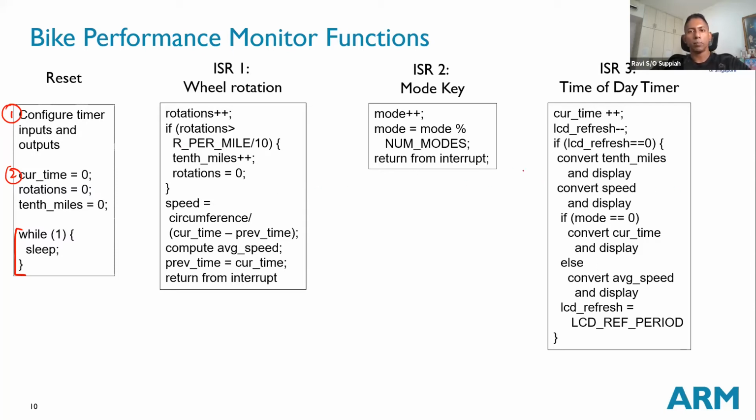Okay, so this mode of operation is good for power consumption, because when you are not doing anything, you allow the processor to go to a sleep or low power mode. That is why in most of your remote controls you can see that the battery can last for very long, 1 year, 2 years, and so on. When you're not pressing any button, you go to a sort of sleep mode. You shut down the LCD display, the backlight, everything. That allows you to conserve power, and when you press a button or something happens, then you activate the processor back into active mode.